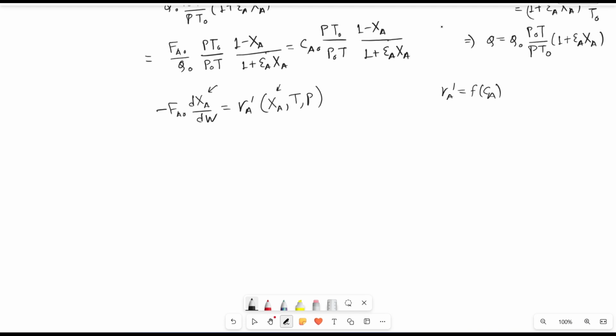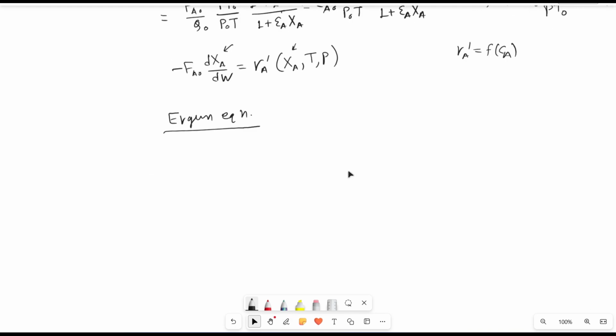The Ergun equation is also a result of momentum balance. It is the final result of momentum balance across the packed bed reactor, but with certain assumptions. This is not a proper derivation, but with some experiment, it is found like that. Now the Ergun equation, we know, is the pressure drop per unit length. The minus sign is because dP, the differential of P, is negative, to get this term positive, because the RHS of the Ergun equation is a positive term. Let me write it properly,